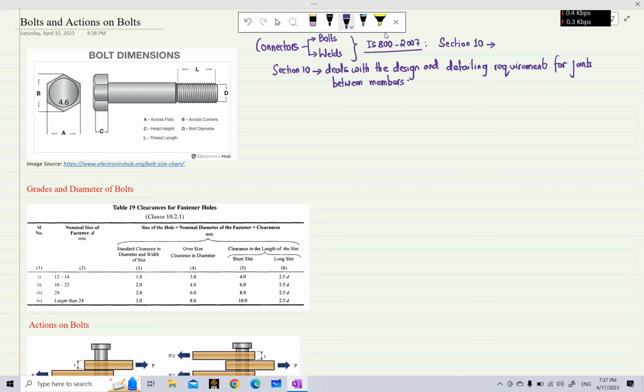We discussed this by looking at 2 cases in our previous lecture: the bending moment diagram of a beam in which the joints were assumed to be rigid, and the bending moment diagram for the same beam in which we had applied releases so that there was no moment transfer. We discussed why it was important to design the connections so that they conform to the assumptions made during the analysis of our structure.